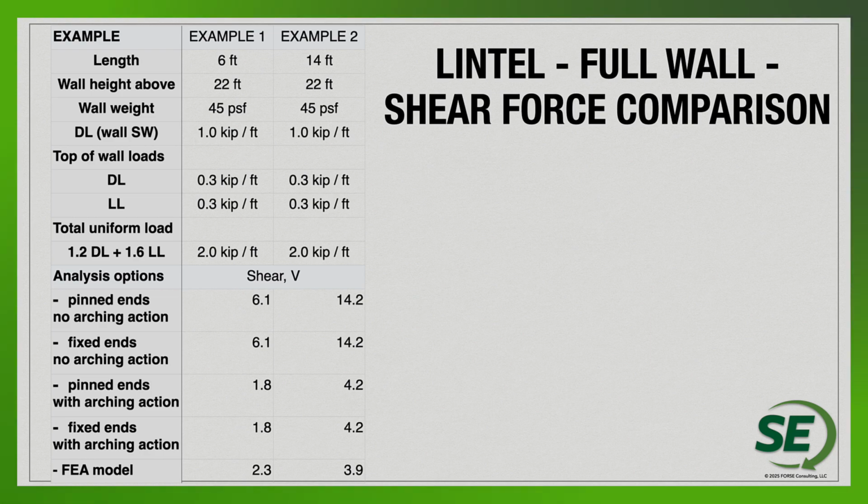You can see the actual shear values that I get. And then what I list at the bottom is different analysis options. So if I consider pinned end, so a pinned end of a lintel element, no arching action, you can see what the shear forces would be for the 6-foot opening. You can see what the shear force is, 14.2, for the larger lintel length. If I have fixed end and no arching action, you can see the shear forces are going to be identical, and that makes sense.